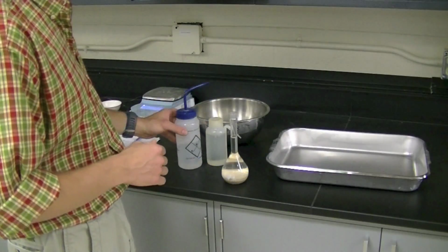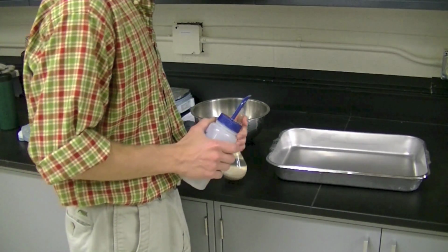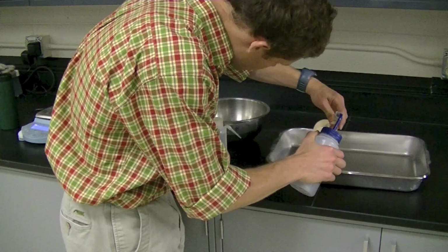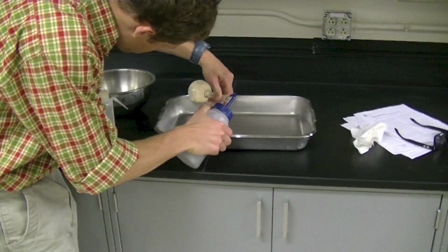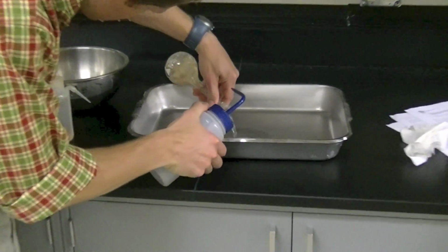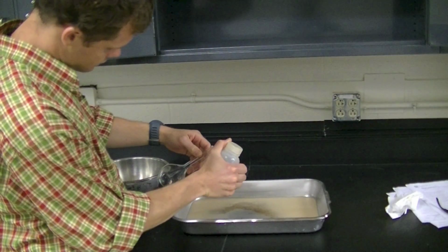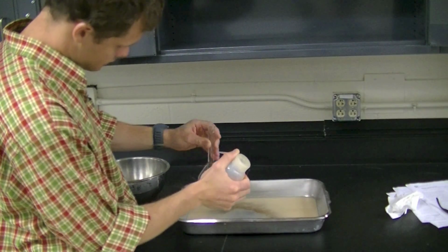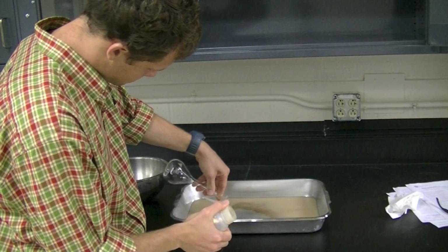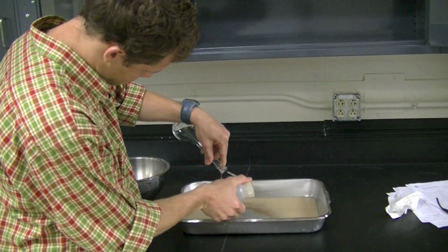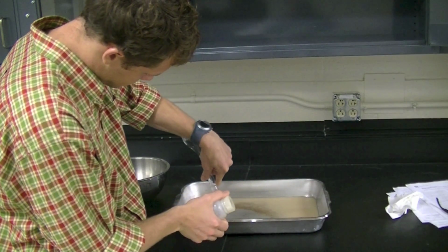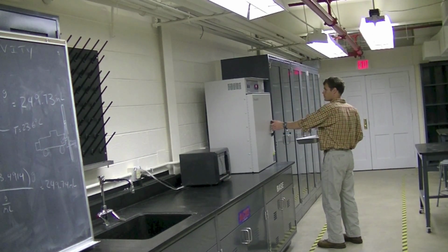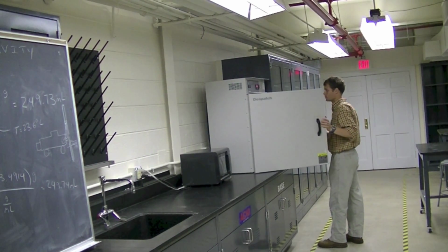Once this has been done, transfer the soil slurry into a pan using a squirt bottle. Remove all remnants and particles. The pan and slurry will be oven dried to obtain a mass of dry solids. After the particles have been removed from the pycnometer, place the pan with the slurry and extra water in an oven and allow for drying at 110 degrees Celsius.